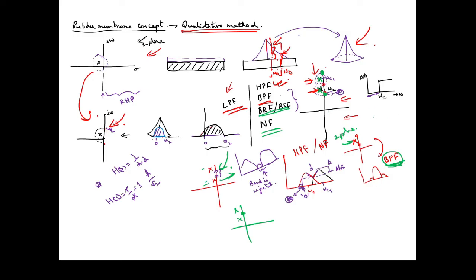Okay, it can be again, as I told you before, the two poles can be placed separately also. So this will help you in increasing the bandwidth of the filter, whereas if you use dual poles at the same place, what you will be having is a central frequency where there will be a high value.